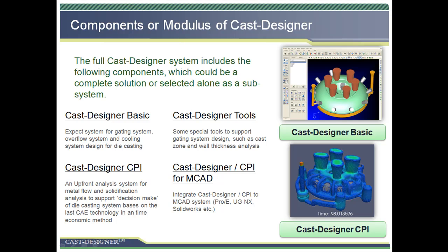The third one is Cast-Designer Tools. These are special tools to support casting system design, such as cast zone and wall thickness analysis. It is optional. There are also other modules, Cast-Designer for MCAD, and Cast-Designer CPI for MCAD. These modules allow integrating Cast-Designer and Cast-Designer CPI into MCAD systems. The supported systems include Pro Engineer of PTC, Unigraphics NX of Siemens, and SolidWorks of Dassault Systemes.